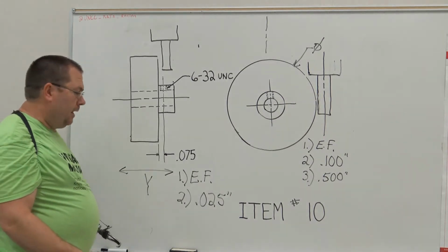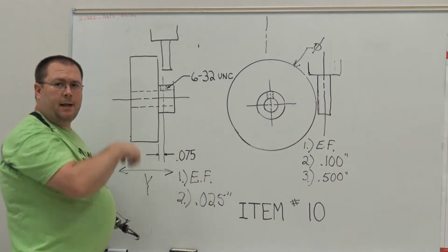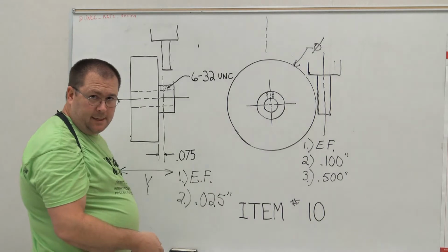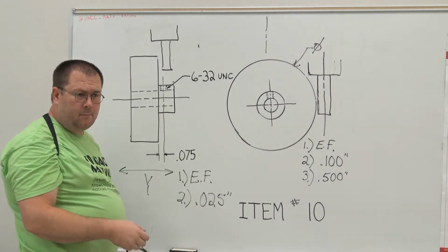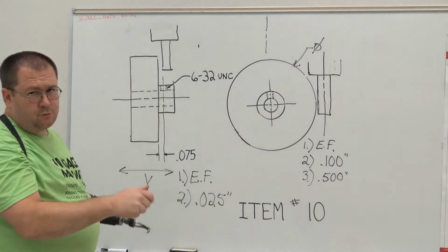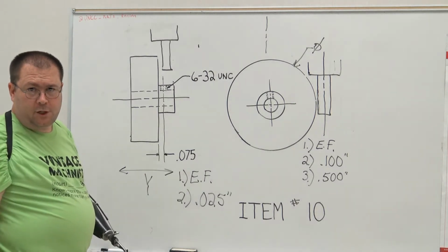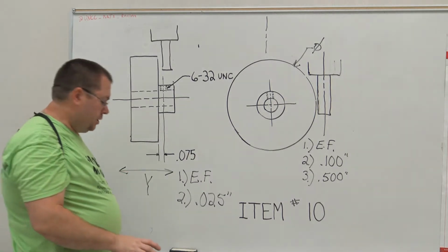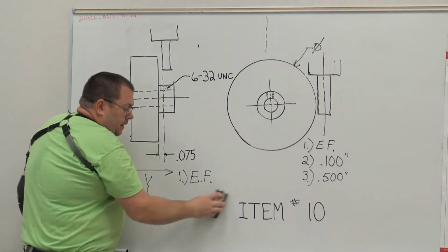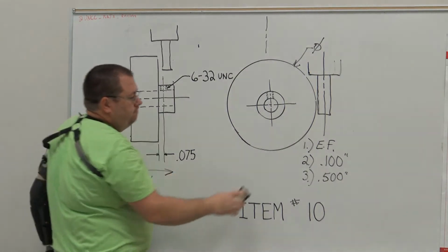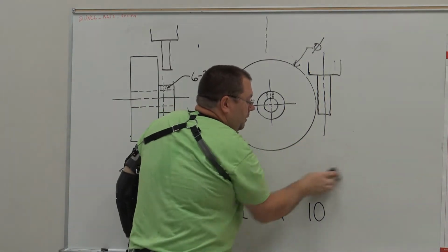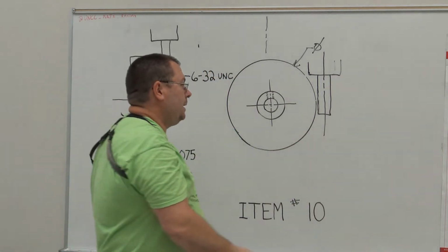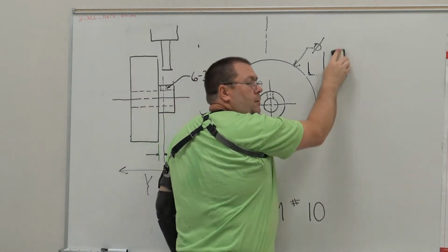So we've done our edge finding. We're not going to be putting a lot of cutting force in, but if you feel more comfortable, we can lock those axes in. Okay? If we lock the axis in, just remember to unlock them before you go to move the machine around again. Okay? So now that we've got our position done, that seemed like it took a lot of time, right? Once you get in front of the machine, that position is something that you can do relatively quickly, okay? So now what I want to do